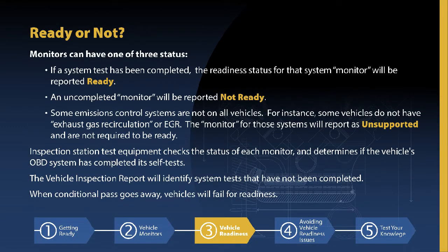If a system test has been completed, the readiness status for that system monitor will be reported ready. An incomplete monitor will report as not ready. Non-continuous monitors that are not used in the vehicle will report not supported or unsupported. Remember, the readiness status of a monitor does not tell you if there is something wrong with the system, only whether the system has completed its self-tests.